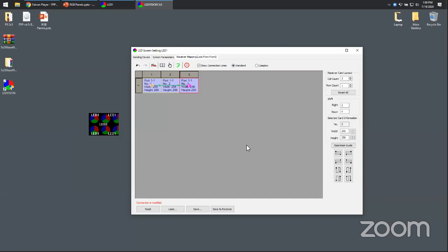It does something different. So you're going to go out of your sending device, which is typically a Pi, into this first one. You're going to go directly out of that one into the next one, and then directly out of that one to the next one in that order. And that's going to create your matrix. So the Colorlight cards know how they are arranged on the grid.